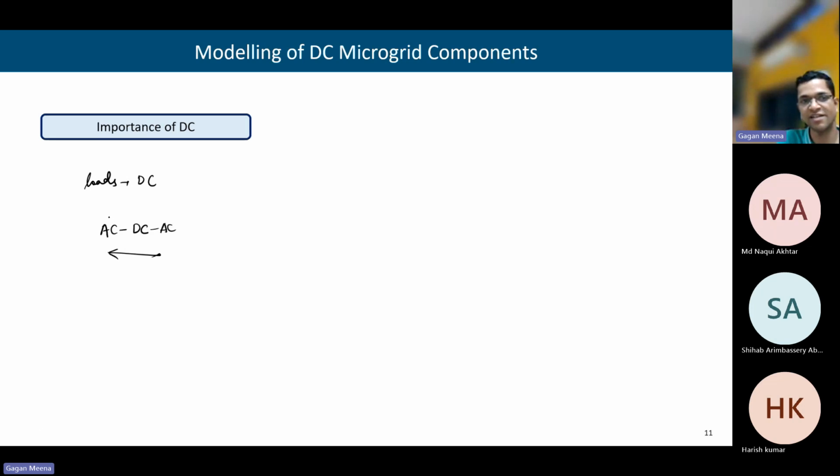While charging, AC to DC, while discharging, again, we will find this in electric vehicles. Two-way loss. If we have a DC fast charger, we can charge directly. So if we have a DC grid, then we can use a DC fast charger and charge the battery directly. No AC stage is required here.